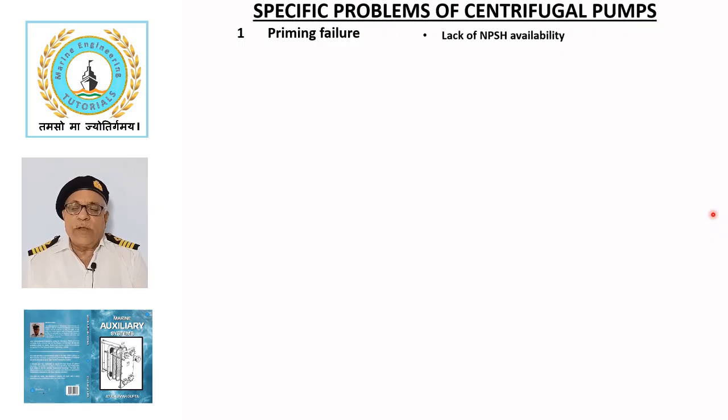To reduce the frictional resistance, suction pipe should have large diameter with smooth internal surface and short length. In addition, it should have minimum of obstructions such as bends and fittings to have clear passage. Large suction pipe diameter used is also helpful in reducing the velocity of the liquid. If possible, vapor pressure of the liquid may be reduced by cooling.